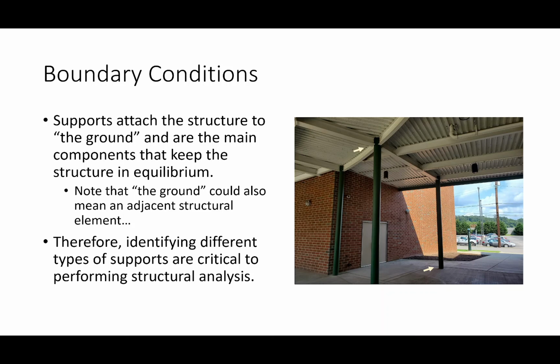So for a pin boundary condition, we're going to see the symbology here in a second, we'll have an unknown force in the x direction and an unknown force in the y direction, but we won't have an unknown moment because it can't resist it. Does that make sense? So the boundary conditions that we assign are a function of what's going on in the real world with the problem.